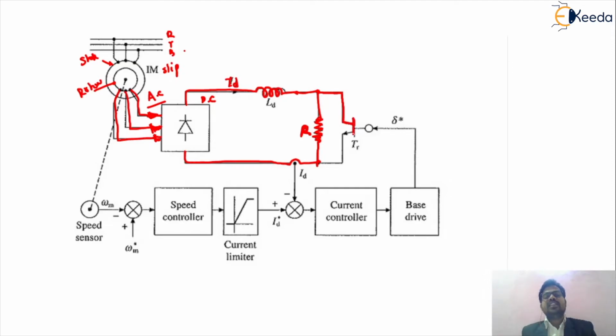As we have seen, this is one type of transistor which has the terminals emitter, base and collector. This power electronic device changes the value of the resistance. While we change the value of the resistance by means of these transistor devices, the speed of the induction motor changes, and this is the speed control strategy that we prefer for the steel rolling mill.